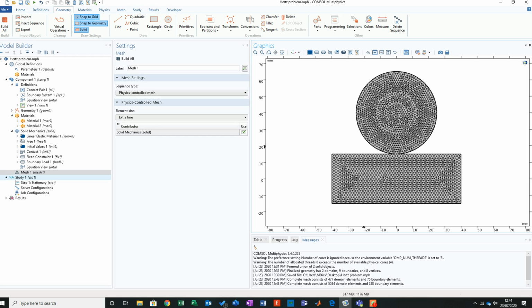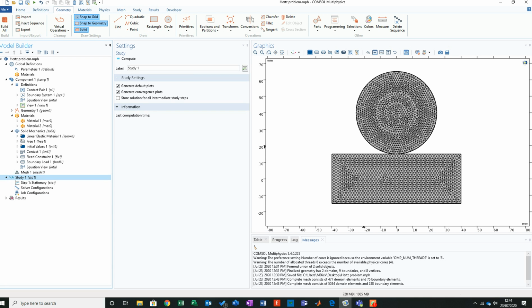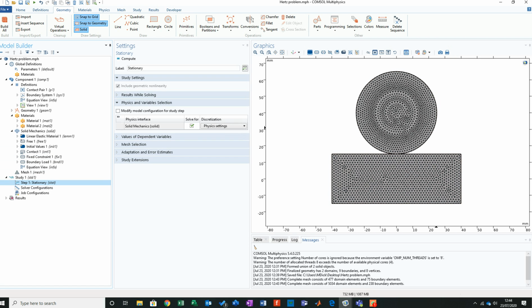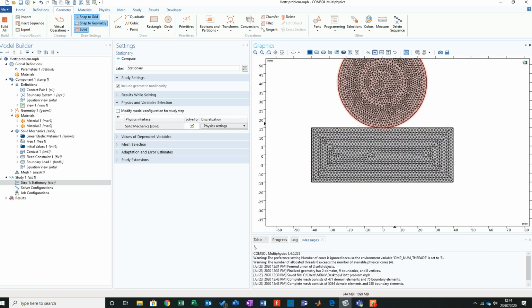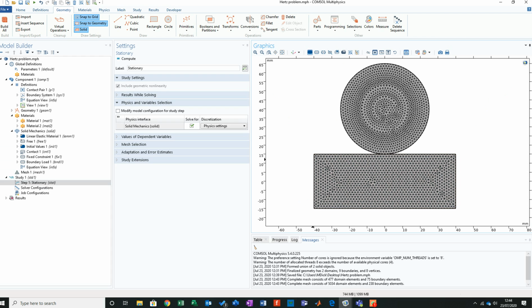Let's take a look at what we're looking at. Now, if I hit run, it's going to run on a particular single state. If I want to look at a gradual build in stress and force across something, there's a few ways you could do it. We could do a parametric study. We could run it under a variable that we've still yet to name, and then systematically record that position every time it iterates to see what's happening, and then record those states and map all those states together to give us an overall of what's happened.